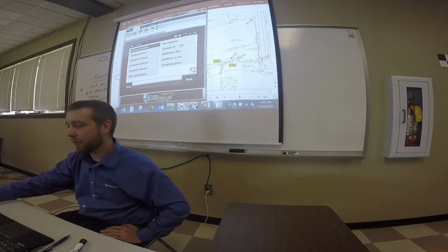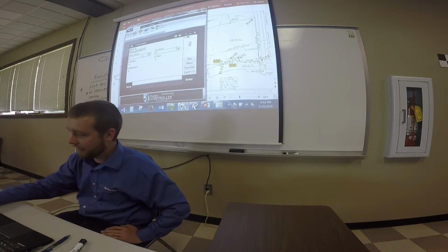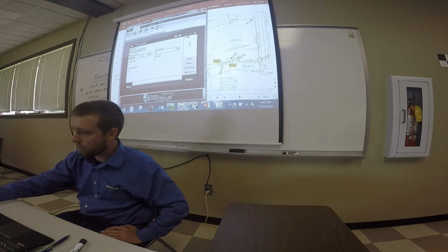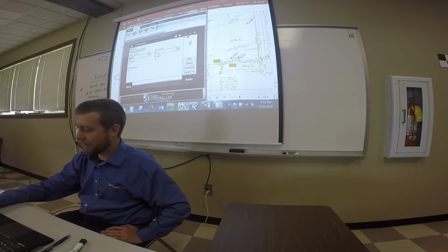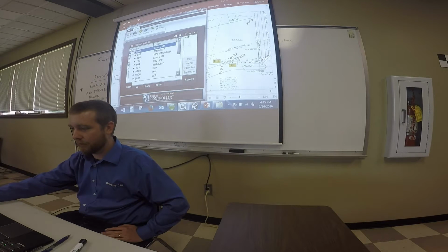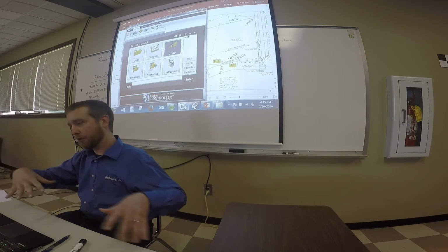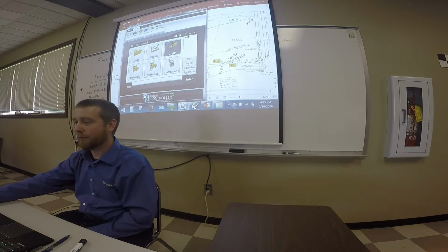Go to Cogo, transformations, we'll translate. Okay, we're going to go from when I just keyed in 9201. We're going to move that on top of 9101. And this time we're going to move 9201. We'll go up here and grab 9108 that I missed. All right, what that did, it just moved 9108 back up to where it's supposed to.